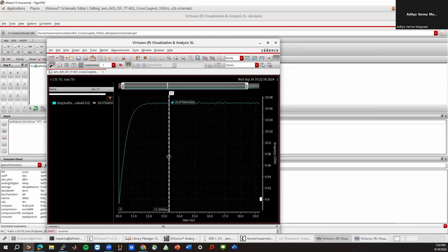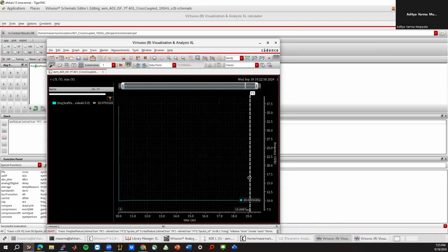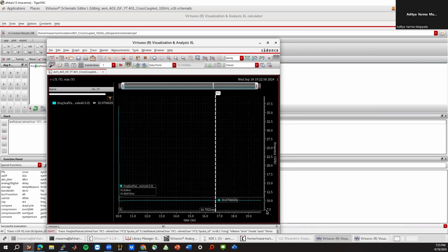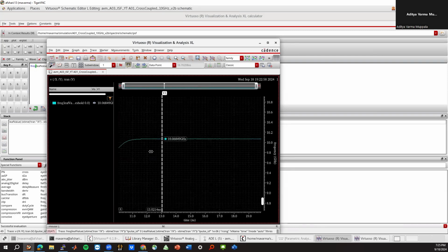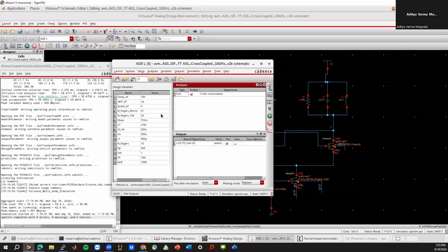So if we look at this and I place a marker, we see that the impulse came in at around 10, and by about, definitely by 11, it's sort of settled, right? Let me zoom in here. Not by 11, sorry, by about 15, I would say it's kind of settled. So what this means is that we only need to simulate up to 16 nanoseconds because we can measure our impulse response at 15 nanoseconds or so. So that gives us another part of the puzzle, which is when to measure, right?